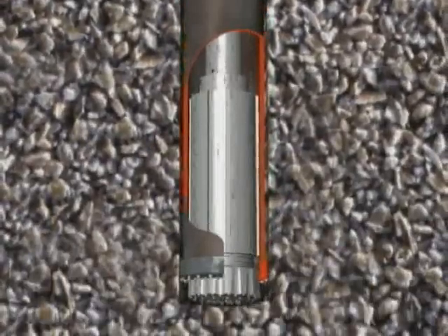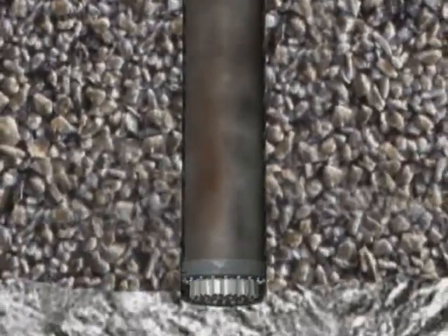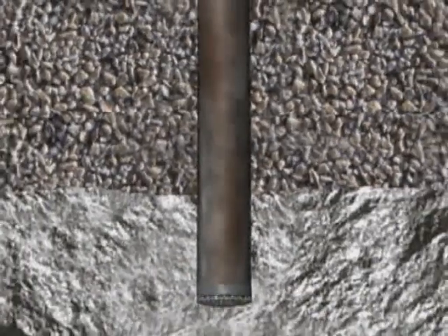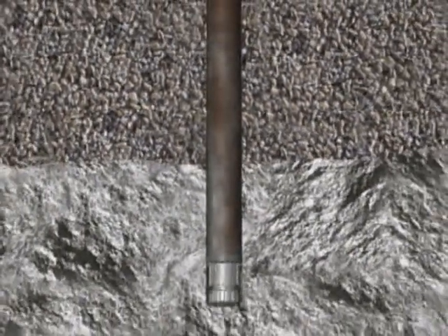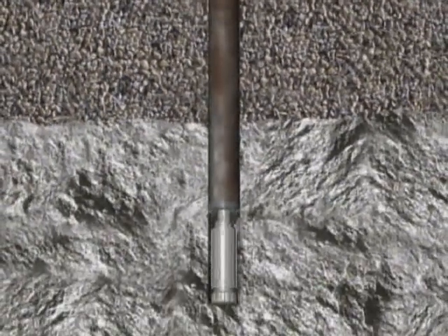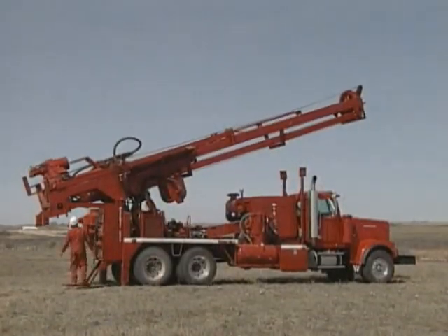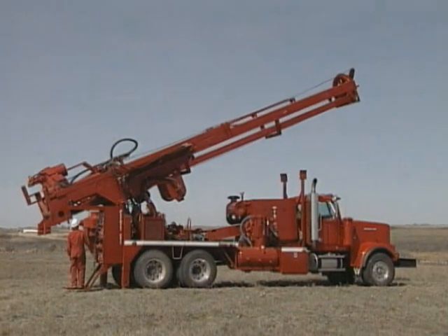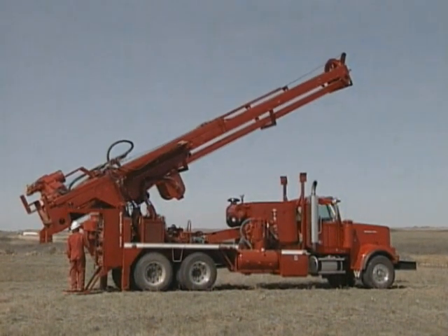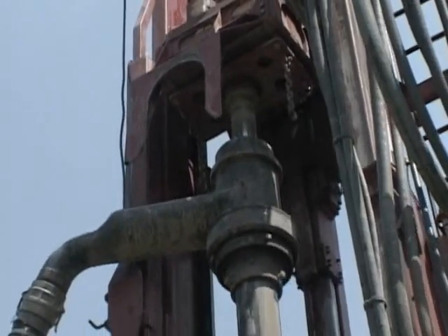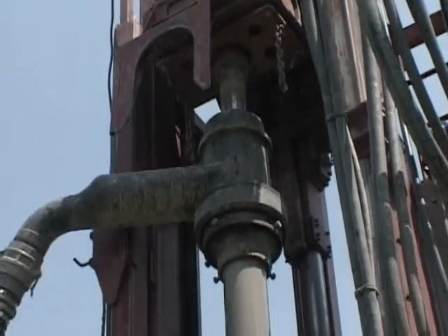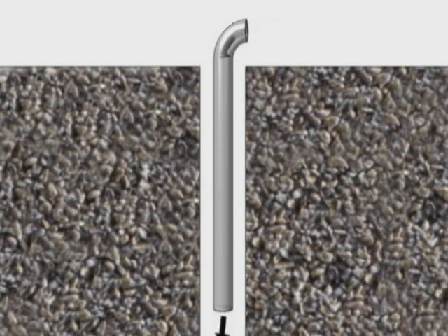Once the desired casing depth is reached, the dual rotary rig continues drilling, much the same way as a conventional top drive air rotary drill. The dual rotary system is a 2-person operation that can use either rotary cut, crush, or percussion cutting actions. Shown here is the rotary crush cutting action. This system utilizes a conventional circulation system with water and air as the flushing media.